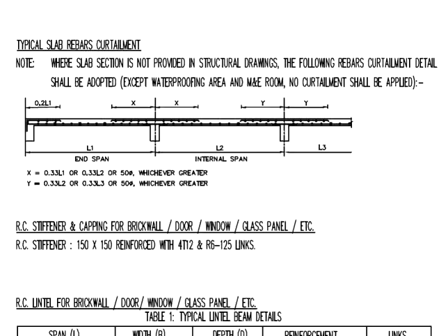Now in the case that you are dealing with the internal span, the required anchorage length here and here shall be in accordance to this. Normally we will put this as symmetrical. Whatever length that you provide on this side, you will arrange it the same for the other side. Same goes to this.